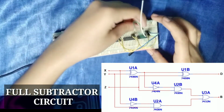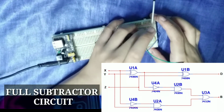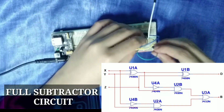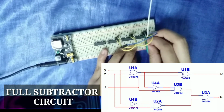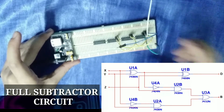Now, connect pin number 3 of the 7486, which is the output of pins 1 and 2, to pin number 13 of the 7486 here. So, pin number 13 is one of the inputs of the 7486.